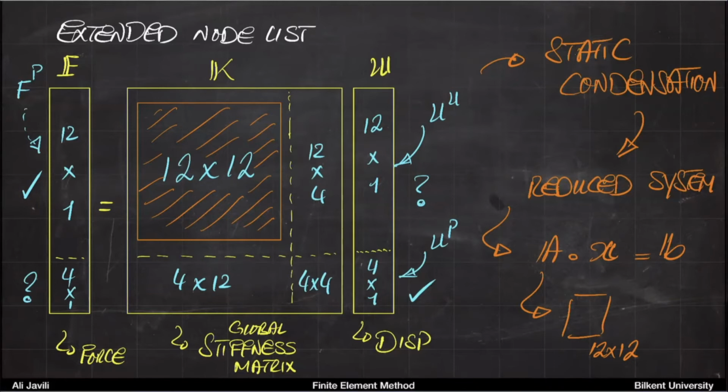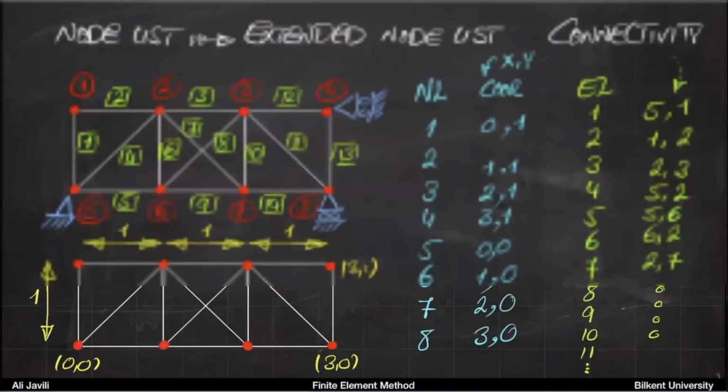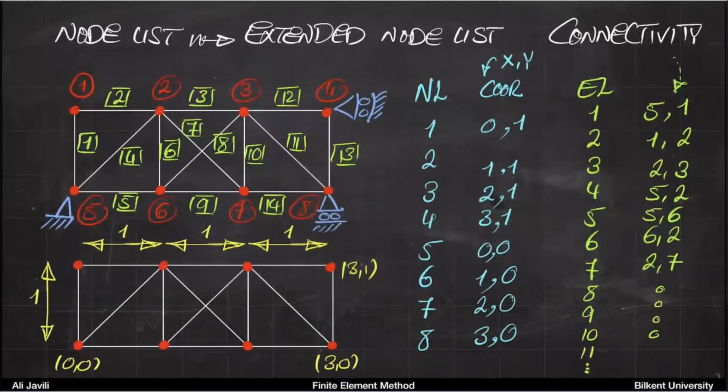After this, we have learned how to handle a two-dimensional structure. Remember what we wanted to do? What we want to do is to learn how to assemble a system like this. It's still made of truss members. So each member is like a spring, a one-dimensional element, but we have it in a two-dimensional space.